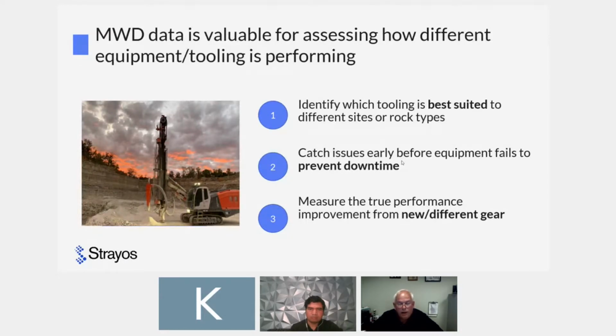Downtime, it helps prevent downtime. You see the productivity of that drill dropping off, it's quantifiable, it's recorded. And you also can measure the performance of new and different changes you make, whether or not you use carbide buttons or if you use ballistic or items like that. And it allows you to measure and actually quantify it a lot better.